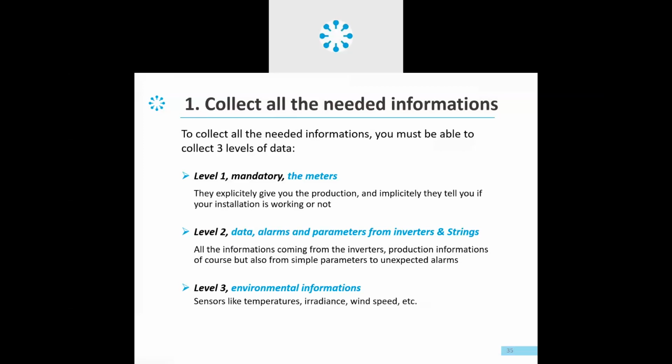Maybe your MPPT was underperforming that day, your inverters were underperforming, or maybe the temperature was high but the radiation was low, which tends to generate less power from the modules. So if you have all this information collected from temperature sensors, radiation, wind speeds, and in some cases even hygrometry, it can be very vital and useful collectively.